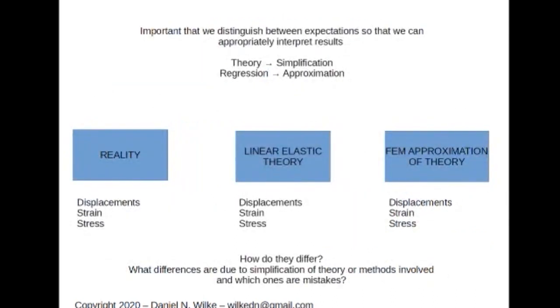Okay. Again, this is just to that aspect that I've driven home in the past a little bit, talking about the reality, linear elastic theory, and finite element approximations. So we are now essentially, theory is telling us simplification of the real world, regression is approximating that theory. We have to have an understanding of what we expect the displacement fields, strain fields, stretch fields to look like in each of these worlds, and how they differ, and which differences are legit, and which differences are because of mistakes. That is really important.